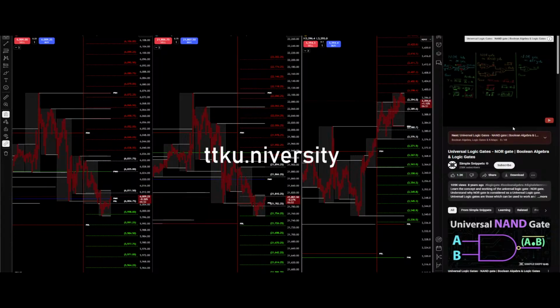Well, the proof is very simple in this case. We provide A two times as an input to the first NOR gate, and there is only one NOR gate in this case. So the output here would be Y is equal to A or A the whole complement. Now we know A or A is always equal to A. So we can say that this is equal to A complement. So as you can see, we provided the input A, but we got the output as A complement. So this is the function of a NOT gate. So hence we have achieved NOT gate function using NOR gate.